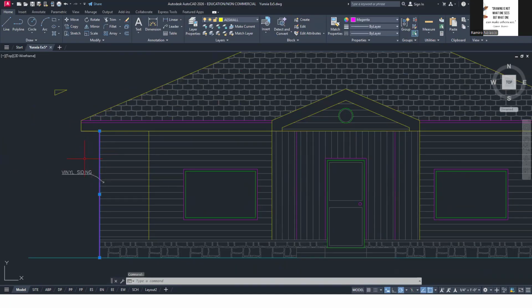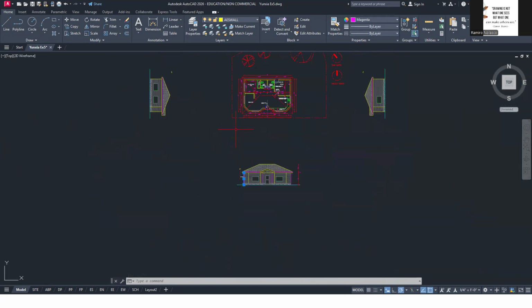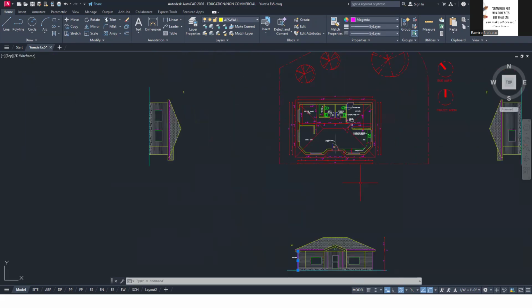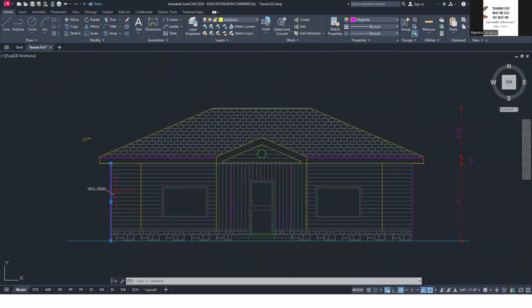Okay. So here, this line is magenta. It's thinner. Why? Because if you look at our floor plan, this is at the back, right? So the farther an object is, to make it pop out, make it a little thinner. So that's why I use yellow here and then magenta there. Okay? So yellow, yellow, and then magenta, magenta, yellow, yellow, magenta. That's the reason why we have those lines here, to show that it is inclining a bit, right?